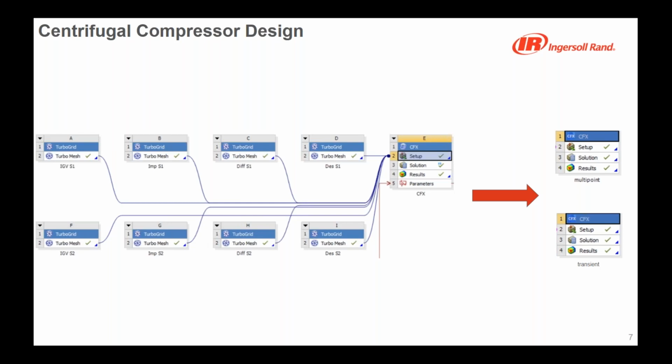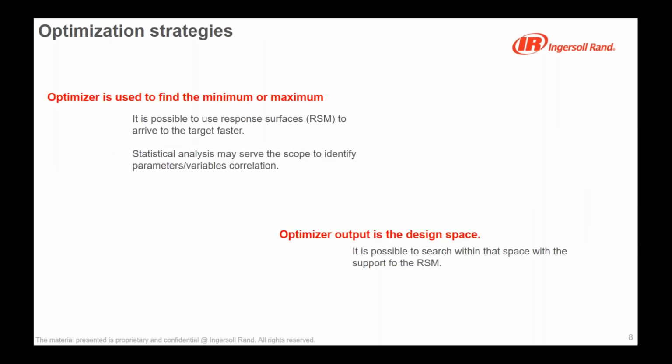The multi-point is an interesting feature within CFX, as launching just one simulation, you can run a compressor curve. And of course, you can then run a transient analysis or mix the two of them. So this is just a very quick overview of what can be within a CFX package when we study a new compressor.